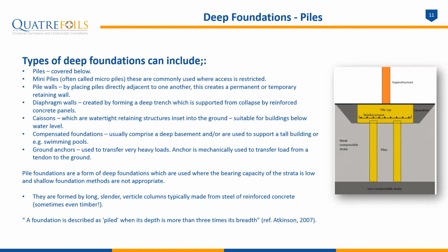So, piled foundations are a form of deep foundation typically used where the bearing capacity of the soil is low, and any of the shallow foundation methods covered above aren't really suitable. So the aim is basically to transfer the load deep down into the ground to reach a less compressible strata to avoid potential movement of the weaker, more compressible soil. This is usually achieved by either driving piles, boring them, or screwing them into the ground to the required depth. They're usually formed by long, slender, vertical columns, typically made of steel or reinforced concrete. In technical terms, a foundation can be described and referred to as piled where its depth is more than 3 times its breadth.